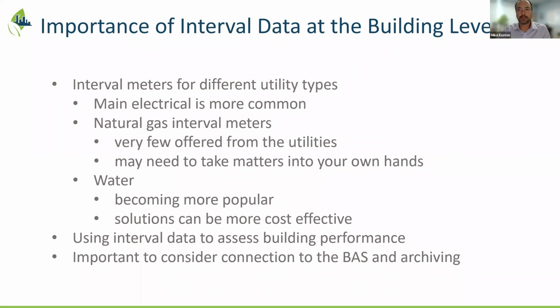Yeah, thanks, Frank. The necessity to integrate with building level water meters from the municipality is increasing as water becomes a much more costly and precious resource. We're probably only seeing about 15 to 20% of municipalities across the country making it easy to integrate with their main water meter, whether that's a technical issue or a procedural issue. When we can, and the City of Toronto is a good example, we can purchase and install new modules on the existing meter that provide a pulse output. The city does need to be involved to reseal the meter after installation.